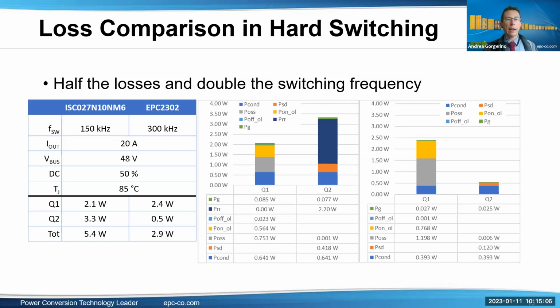And the reason for that is that GaN FETs switching faster, again, this is done with the same gate driver, same assumptions. You can use lower dead time. The assumption for dead time here was done in the similar way for both devices. Basically, it's 2 times the sum of all the transition times to give some margin. And again, since the GaN FETs are switching faster, the dead time tends to be much smaller. And this means you spend less time in that condition, which means lower losses overall.